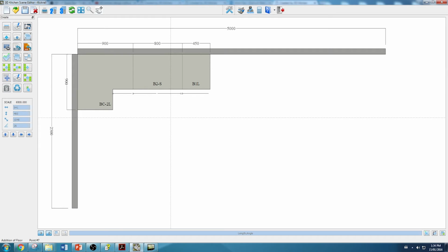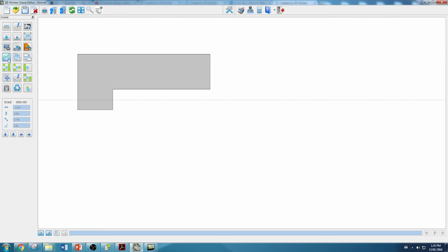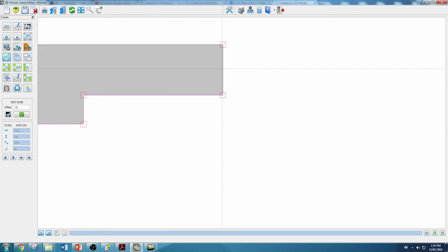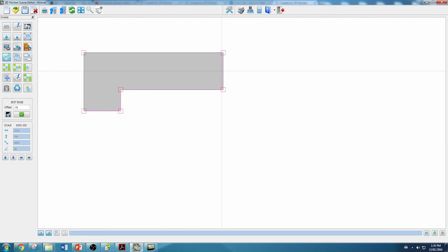This procedure must be repeated for each separate piece of kick rail in your design. Click the polygon editing icon. This will display the kick rail pieces. Click anywhere on each piece of kick rail. Click inside the edge of every edge you need to edit. Click multiple edges only where they will be edited by the same value. Chosen edges will be highlighted with a different color.